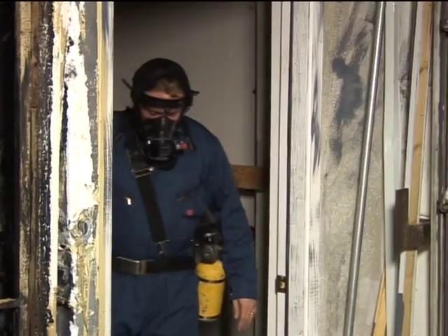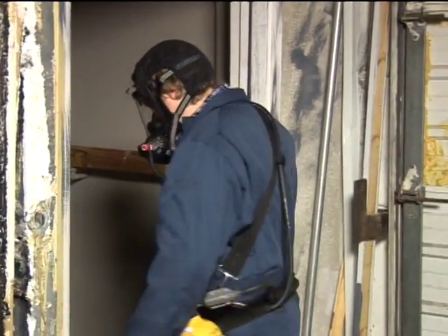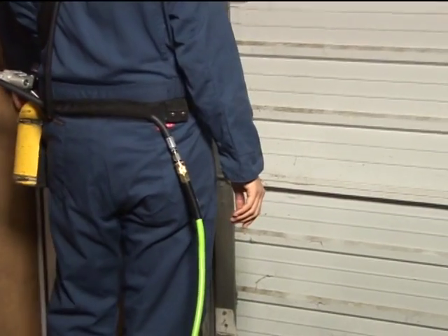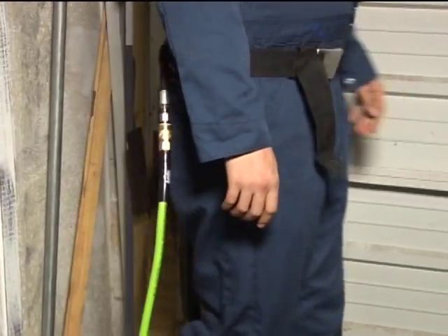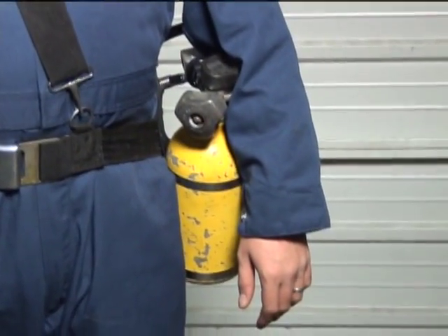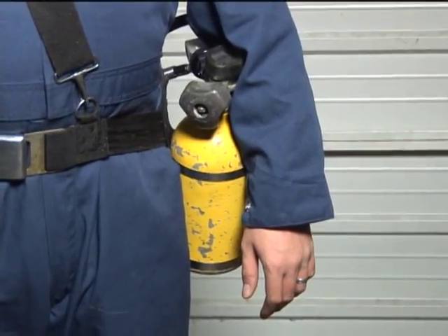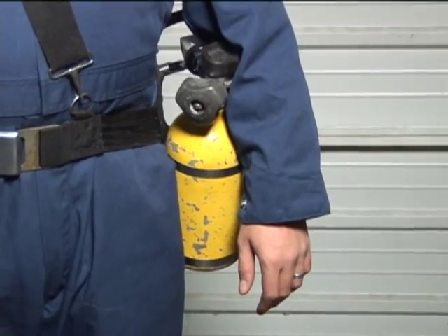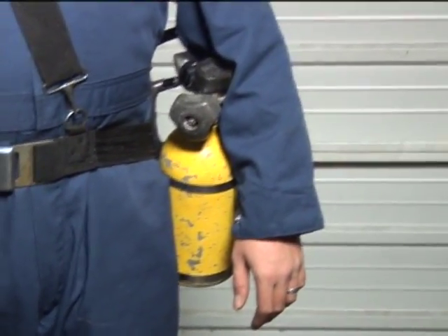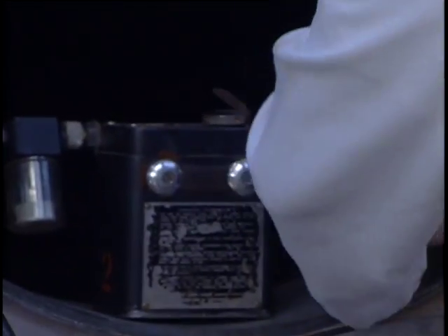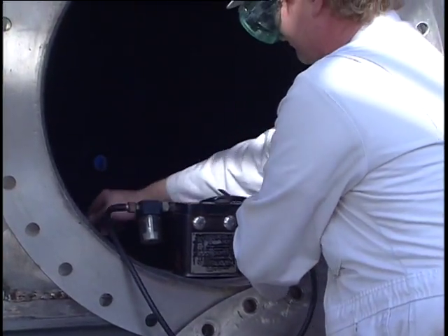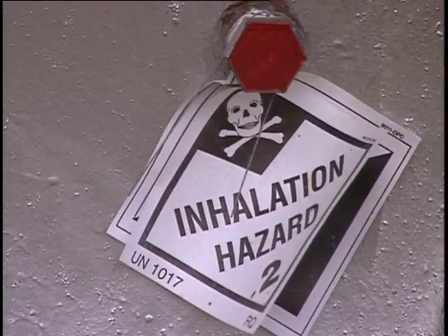A combination respirator has an air supply component, plus an auxiliary self-contained air supply to be used if the primary supply fails. The self-contained portion can be small, since it only needs to supply enough air for escape, and usually has enough breathing air for a few minutes in a self-contained tank. These respirators can be used for entry into confined spaces and are normally used when there are extended work periods required in an IDLH atmosphere.